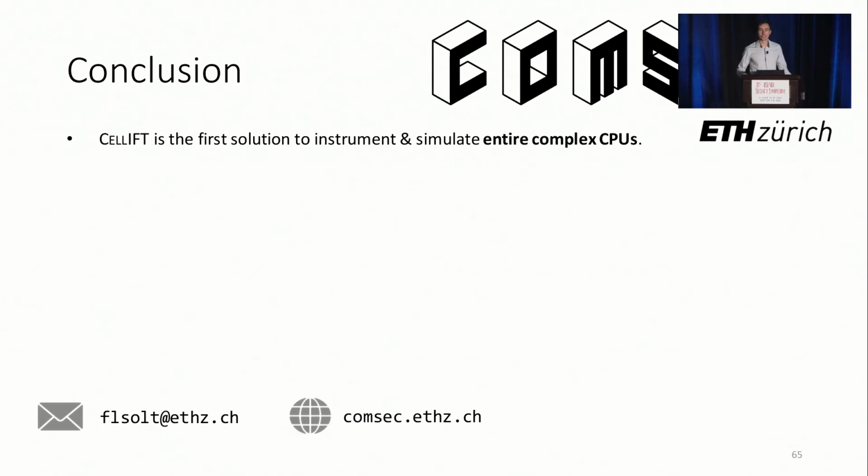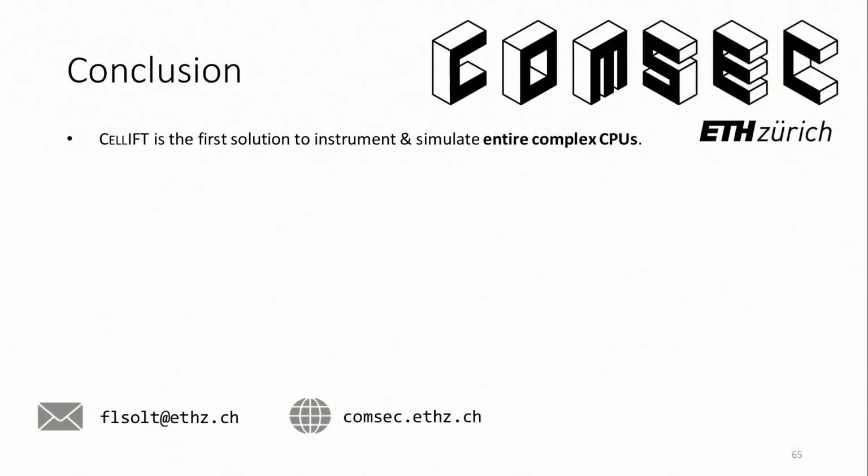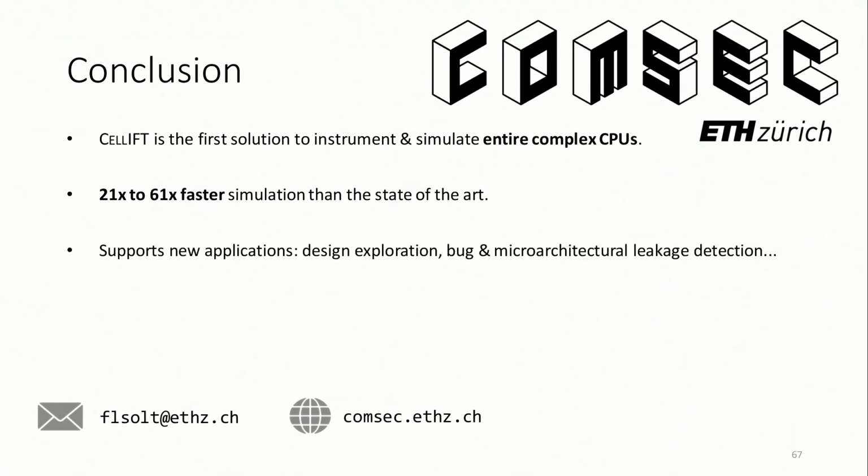OK, time to conclude. CellIFT is the first mechanism that can instrument and simulate out-of-order CPUs, or any CPU that we could try, at the time of the writing at least. It's much faster than the state of the art for some designs that could already be instrumented and simulated. We have new applications. So for example, detecting leakage through Meltdown, through Spectre. But we are convinced that there are new applications that we did not think about, or that we are working on right now. We don't know if they will succeed. But there are new applications.